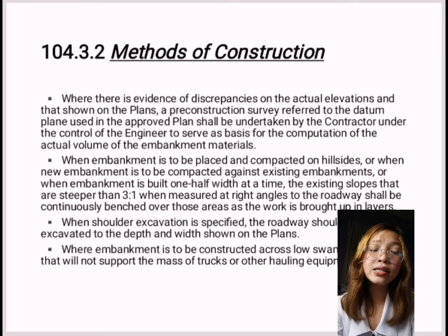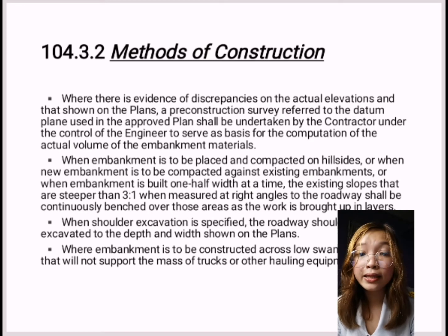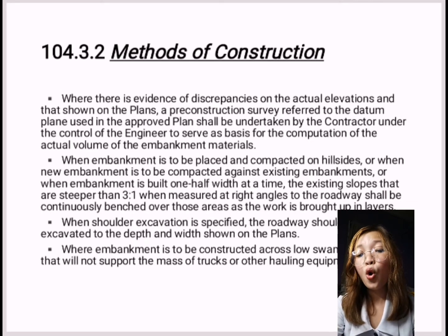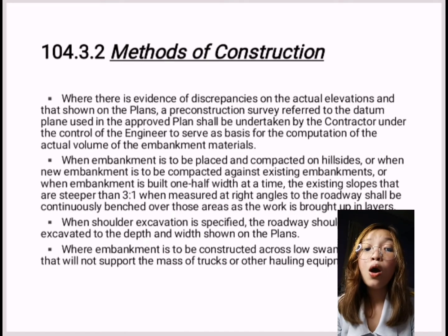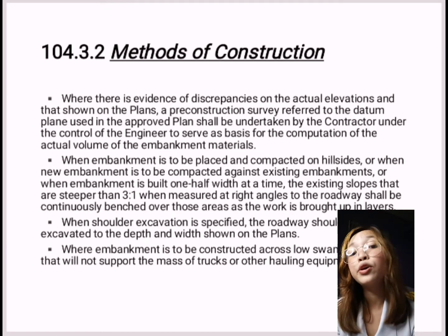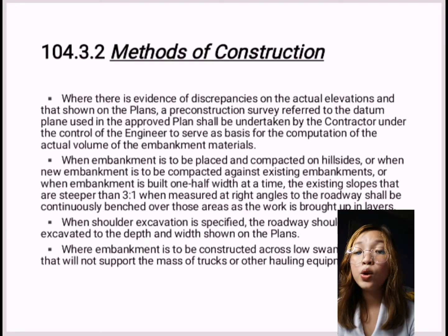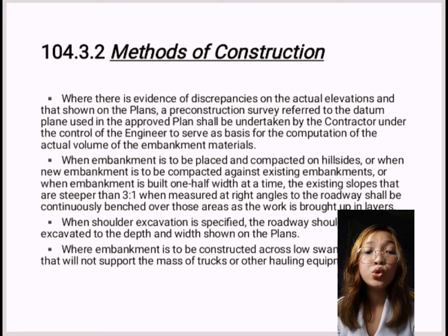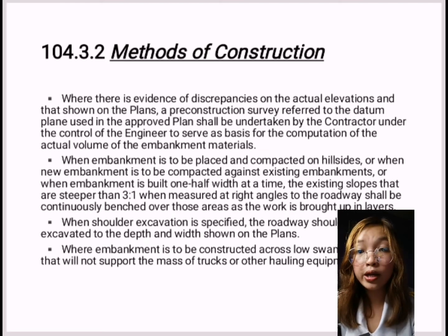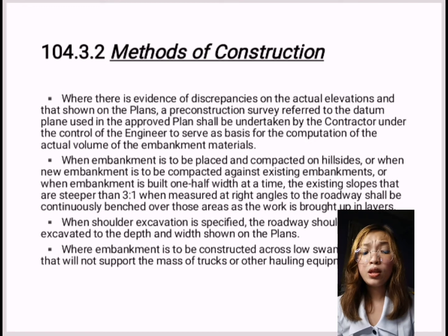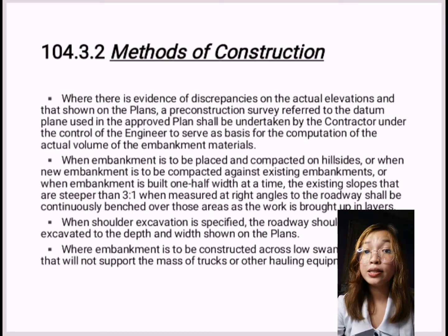Next, when embankment is to be placed and compacted on hillsides, or when new embankment is to be compacted against existing embankments, or when embankment is built one half width at a time, the existing slopes that are steeper than 3:1 when measured at right angles to the roadway shall be continuously benched over those areas as the work is brought up in layers.